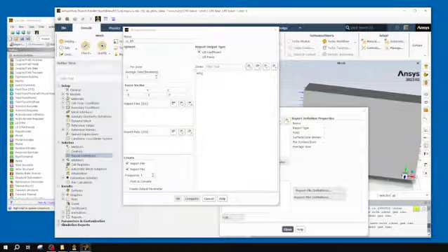Down here, you'll see a couple different options. You can make a report file, report plot, print to console, and create output parameter. The biggest one I do suggest is we do want it to print out to our console, and I generally change this report plot, or no, I do want this report plot to be 1, so it updates every point that it's reporting. So that should be good. Oh, for zones, I just needed to select wing, since it's the only option for me. But now I can click OK.